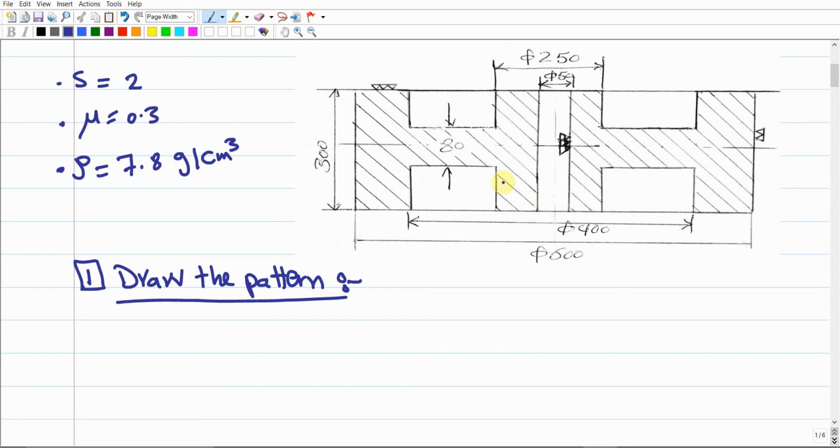you should understand what the shape of the final product is in terms of engineering drawing. Generally in engineering drawing, any product that can be represented using only one projected view is a cylindrical product or cylindrical object. Any cylindrical object can be represented using only one projected view, and there is no need for 2 or 3 projections. So here we have only one projected view of this product. It means that intuitively it should be a cylindrical shape. And this is very clear from the phi that is given here. Phi indicates that this is a diameter, which means there is something circular.